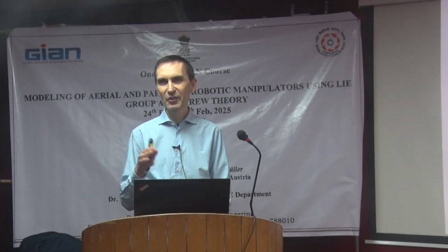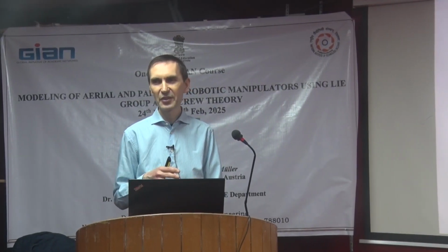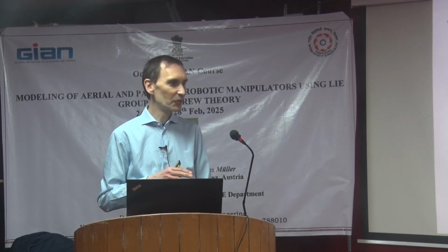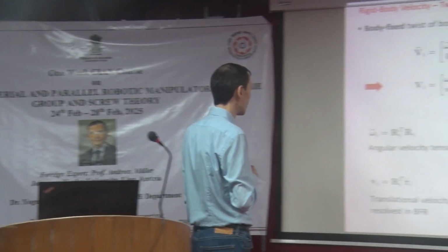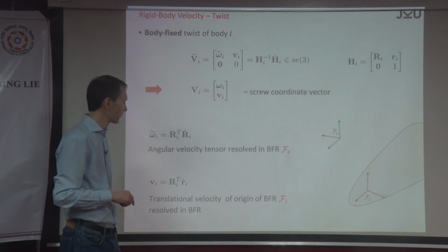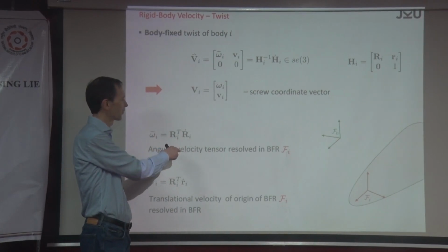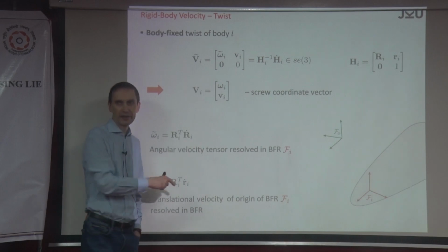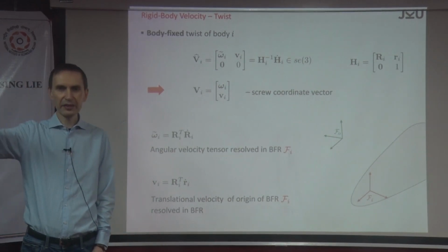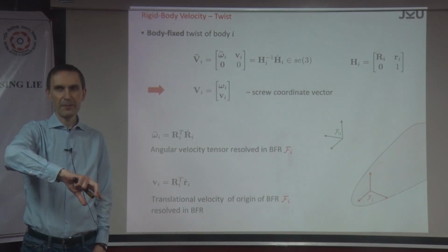Angular velocity is always something you can discuss for ages and still not agree on. So the basic idea is the following. Let's say you have a rotation matrix, and I skipped the 0, so it is R0I. This gives you the rotation of a frame, of a body, relative to the inertial frame.